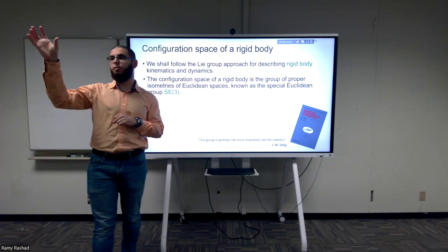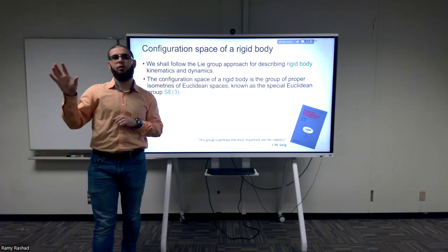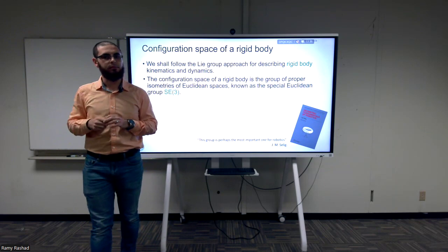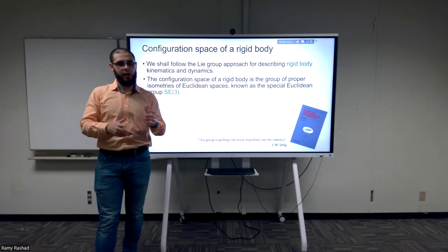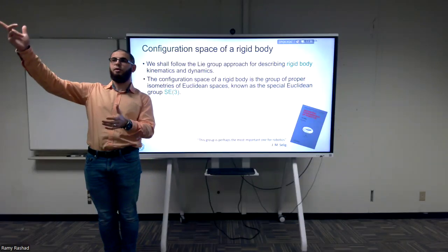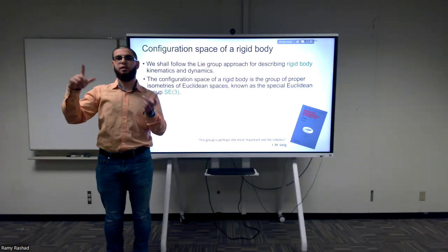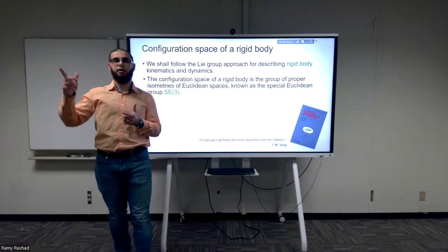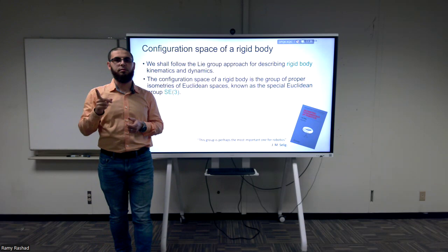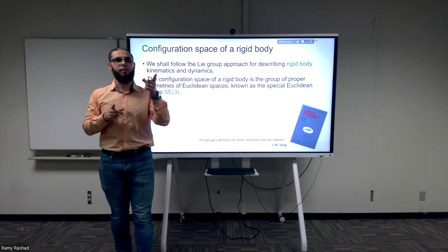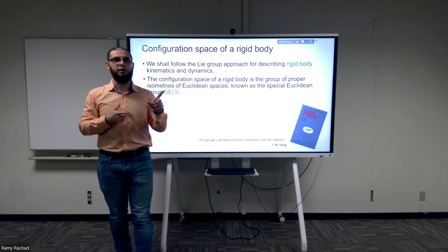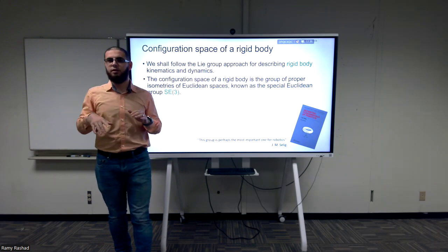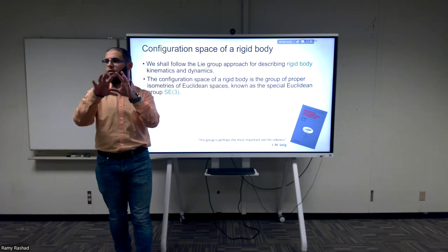If I give you one rigid body alone, how do you represent this configuration? Okay, specify a frame, put some frame fixed on the ground, put some frame fixed on the body. How do you describe this relative orientation and position of the body? Transformation matrices, okay. Who here is familiar with transformation matrices, homogeneous matrices? Okay, very good. So just 4x4 matrices.